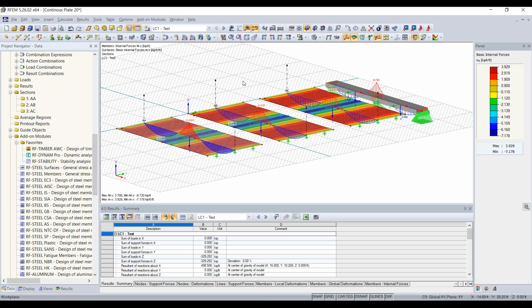Of course, you can draw a surface with the relevant materials and properties for a semi-rigid diaphragm, but it's not an actual diaphragm element in the program. It's really just a surface or a plate element, and we don't provide the analysis with chords and collectors and things like that at this point. So it's just purely FEA. So hopefully that answers that question too. Okay, I think that's it for now.